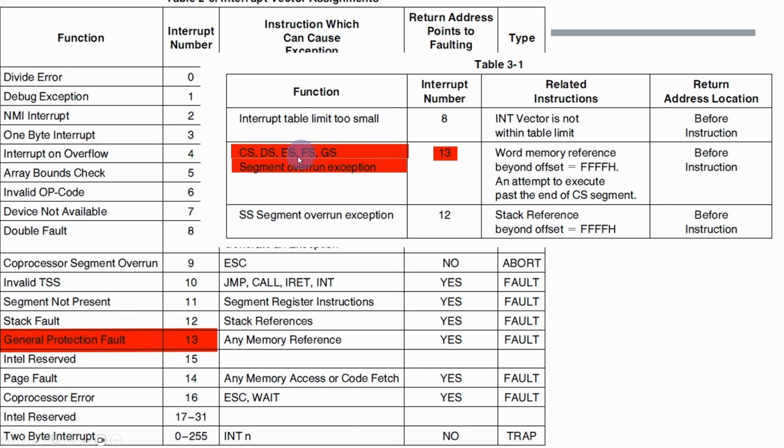What this indicates really is that although the processor is emulating the original 8088, it's not actually doing exactly the same thing as what the 8088 does. So in fact, we can't use the no operation code in the current form to be able to provide a nice test of the processor. But what it will now do is load the segment address off the data bus,